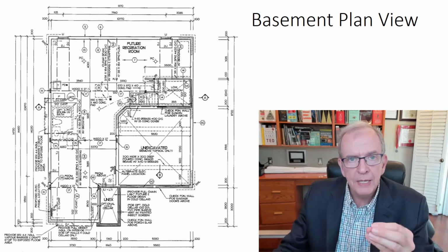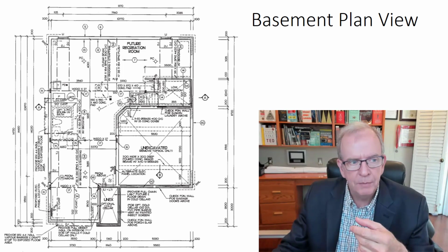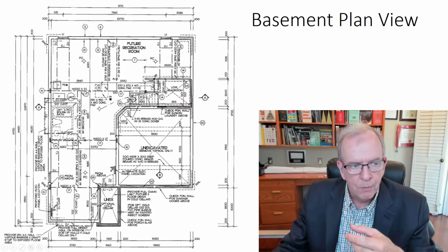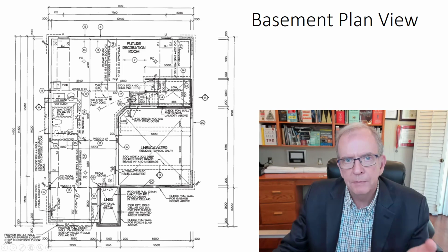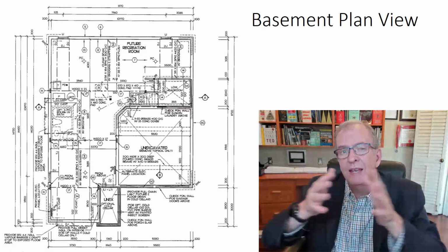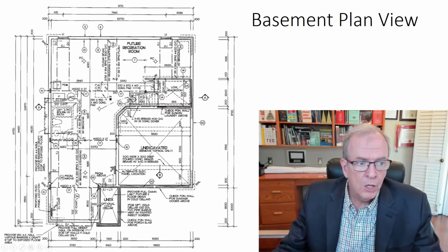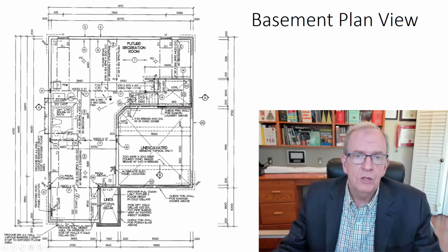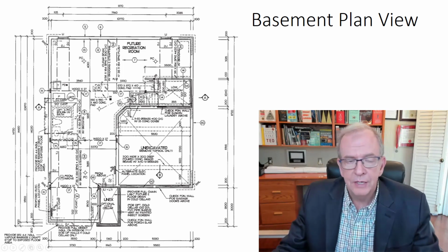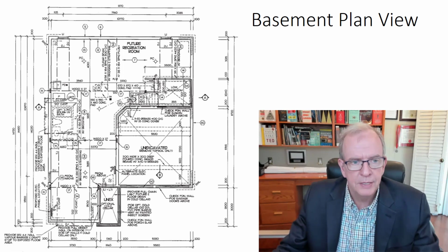The heavier the beam, the stronger the beam. So if I had a W200 that was more than 27, it would typically be stronger. If I had it less, it would be less strong, able to span a lesser distance to support the weight up above. You could easily find out what the beam weighs if you know how long it is, and then you multiply it by that number, and then you have an idea how much it actually weighs if you're trying to figure out how to move it into place, etc.